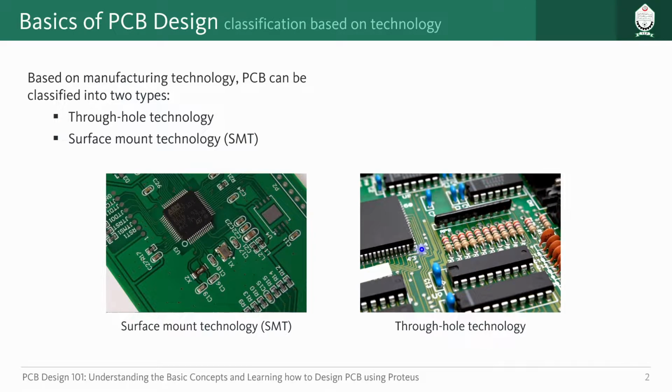So this is through hole technology, and another one is the surface mount technology, which is a recent technology, and most of the time the circuits we see today are surface mount technology. In surface mount technology, all the components are connected on the surface. All the components and all the pins are connected on the surface like this. Like let's say this resistor or this IC, all of them are connected on the top surface. So this is SMT or surface mount technology. But for our purpose today, we are just going to design one through hole technology PCB.